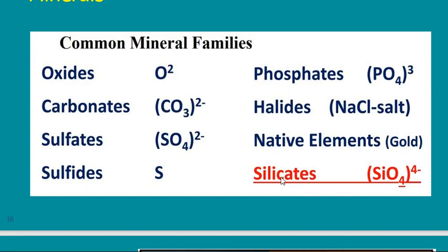The opposite is silicates. When you go to the site, you will find a term. They will tell you, you have here siliceous sand. In Arabic they say raml silisi. This is very famous in sites. When they tell you that I have siliceous sand, it means that the origin of the sand is silicate. So it will not change with time. It will stay as it is all over the time.